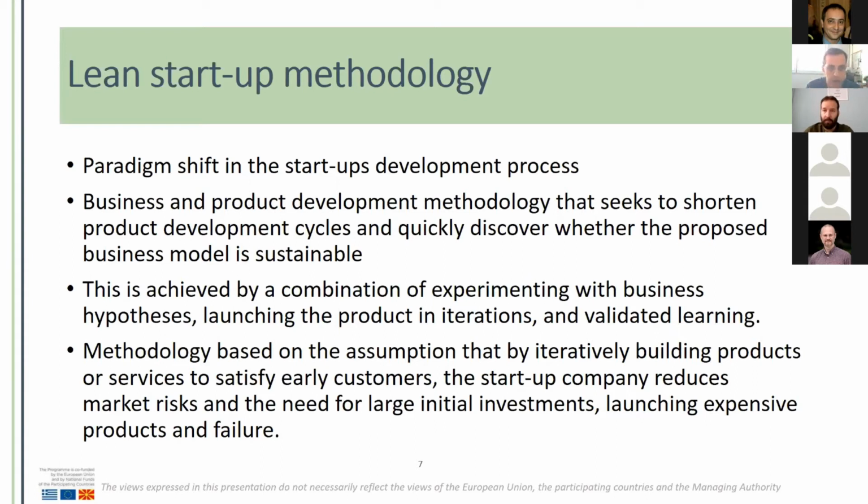I'm not sure how familiar you are with lean manufacturing. It is a production method that is based on 5 key principles. That's precisely specify value by specific product, identify the value stream for each product, make value flow without interruptions, and let customers pull value from the producer. And the 5th one is pursue perfection. This lean manufacturing philosophy comes from the Toyota production system, combined with some other principles like 5S and just in time, Kanban, Kaizen, all these other Japanese business technologies.